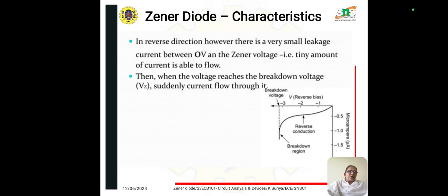Avalanche breakdown is a phenomenon that occurs both in the ordinary diode and in the Zener diode at high reverse voltage. For a high value of reverse voltage, the free electrons in the PN junction diode gain energy and acquire high velocity, and these high velocity electrons collide with other atoms and knock electrons from those atoms. This collision continues and new electrons are available for conducting current, thus the current increases rapidly in the diode. This phenomenon of sudden increase in the current is called the avalanche breakdown.